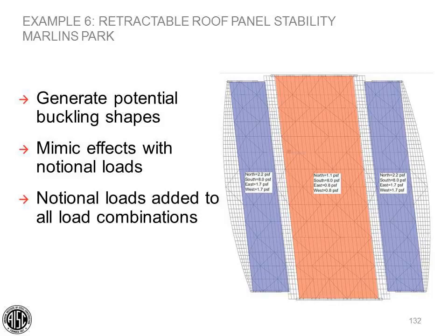We applied the notional loads at the level or at the area that we were stabilizing the trusses with, and the top chords are the ones that are in compression. That's why we applied at the top chord only. I guess you could consider applying the notional loads at all the different locations loads are applied. That would be appropriate as well and could be done, but we just simplified it by applying all the notional loads at the top, which we felt would be conservative.